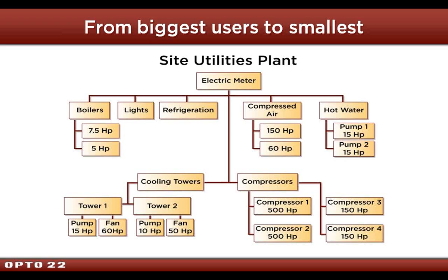I've sat through talks of people on instrumentation and the accuracy and the calibration and all this. You may need that to do meter quality measuring, but we never did it because we have the check, and that's the meter. Every dollar you pay goes through the meter, and no matter what's happening in the plant with our software, and we eventually developed software that mirrored what we did physically in the plant in terms of analysis and all that. But our software will add everything together in the plant and compare it with the meter, and if it's only off a couple percent, that's good enough for us. We don't have to have the very expensive meter quality instrumentation.